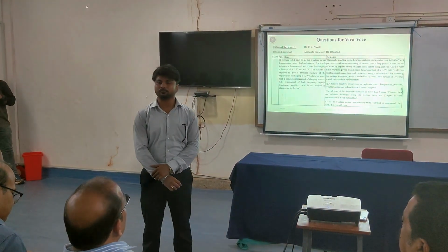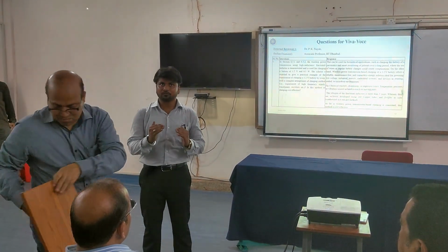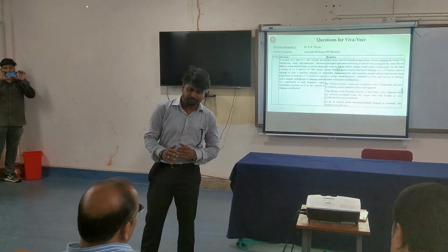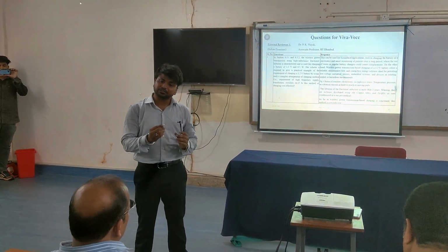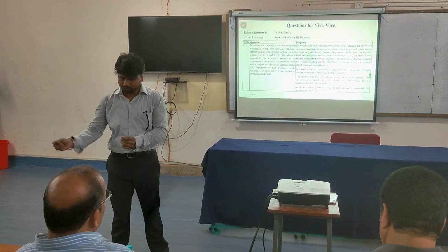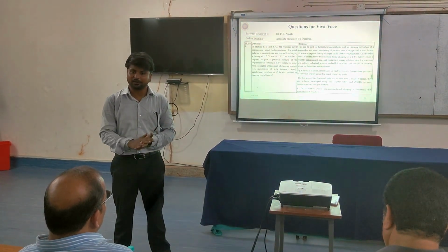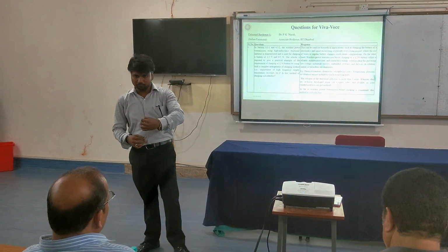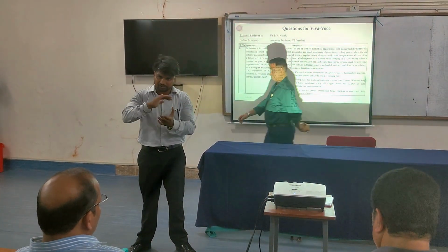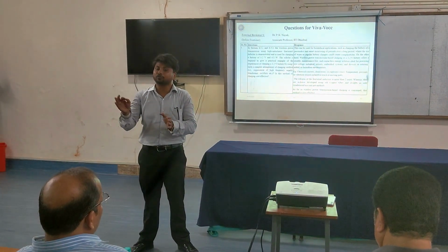So experimentally, our key goal is first to have an order less than 1. For a generalized core-based fractional inductor, it is not yet possible to get that order. Therefore, we are using the TEM model, the transverse electromagnetic mode model. We have a copper tube, in between that a copper wire, and there is a conducting core in the rest of the parts. In that case, it gives an order of 0.5.